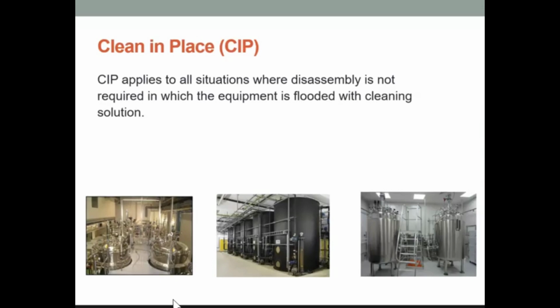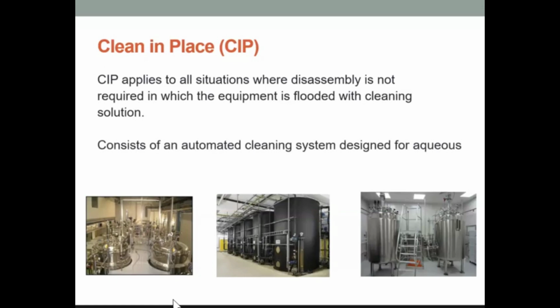Clean in place, CIP. So CIP applies to all situations where disassembly is not required. In this case, you're able to clean it in place and the equipment is flooded with cleaning solution. This consists of an automated cleaning system that is designed for aqueous cleaning.